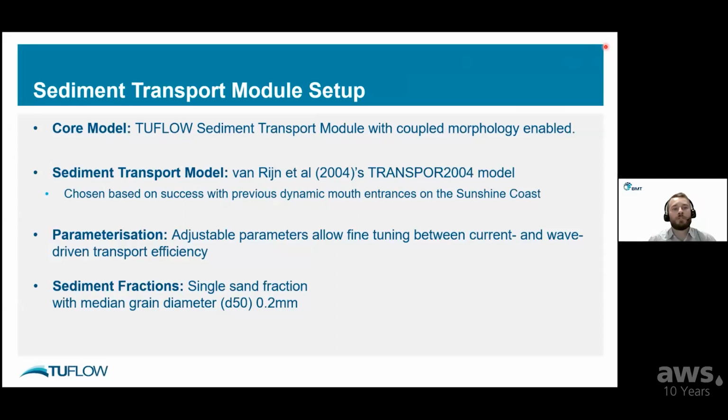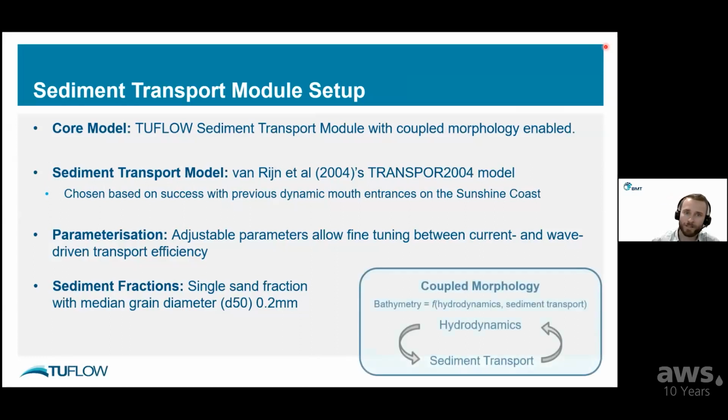So getting into the setup of the sediment transport model, we used the Flow sediment transport module, and we had it with coupled morphology. Here's a little schematic that shows how coupled morphology works. The hydrodynamics provide the information that the sediment transport module needs to calculate sediment loads and transport rates. And then these transport rates update the bathymetry, which the hydrodynamics consider in the next step.